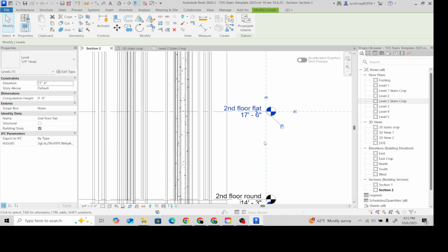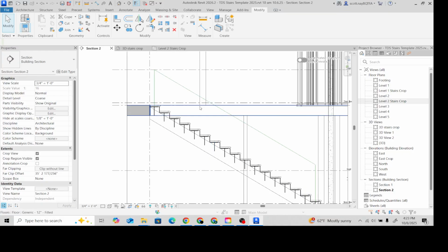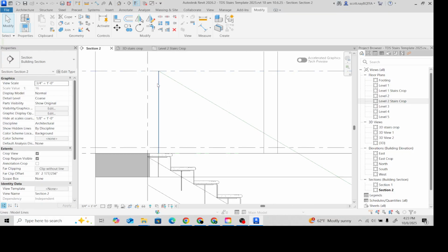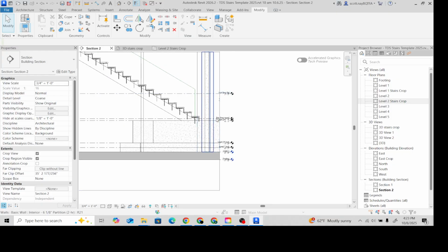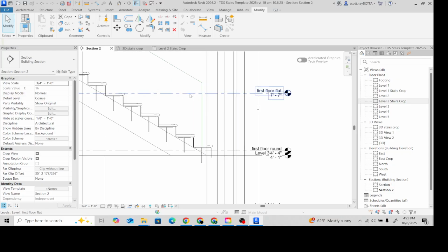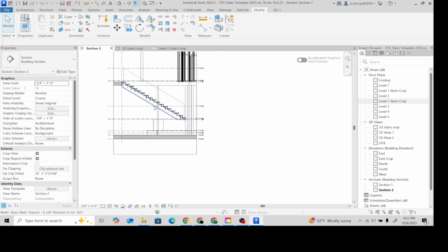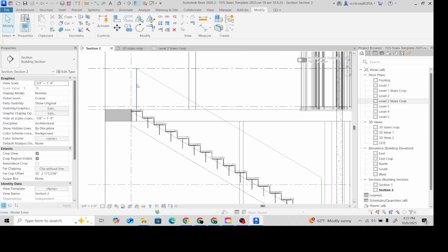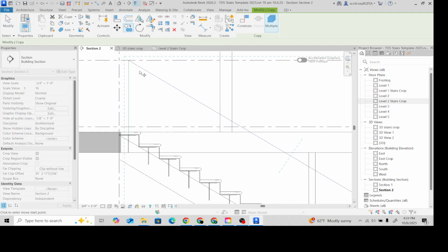The reason we're doing all this ahead of time, just like when we made the openings parallel: if I have 42 inches up here and I have some random height down here, I'm not going to be able to just copy. I'm going to have to keep drawing custom vertical supports, and I don't want to have to do that. So now that we got these established, we're going to take our top diagonal line and copy it once all the way down until we snap on this line.